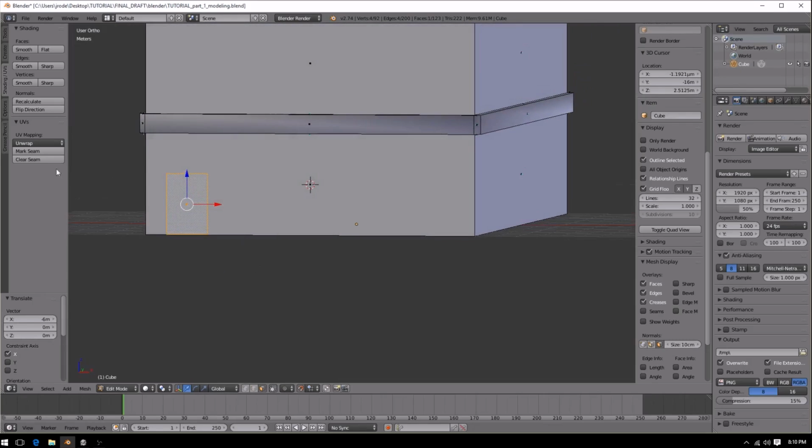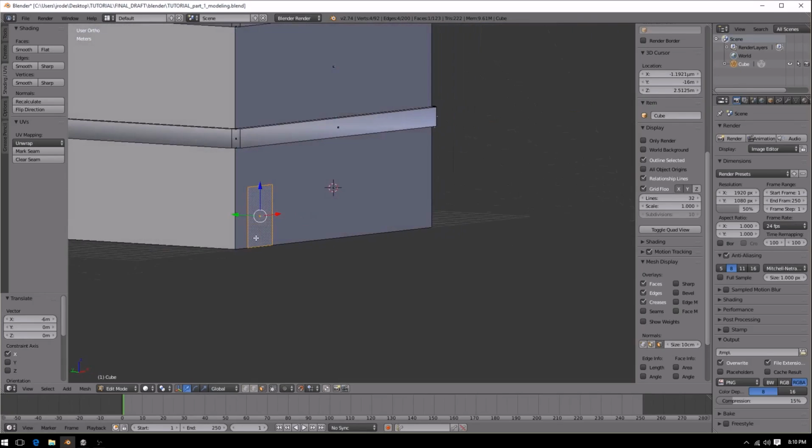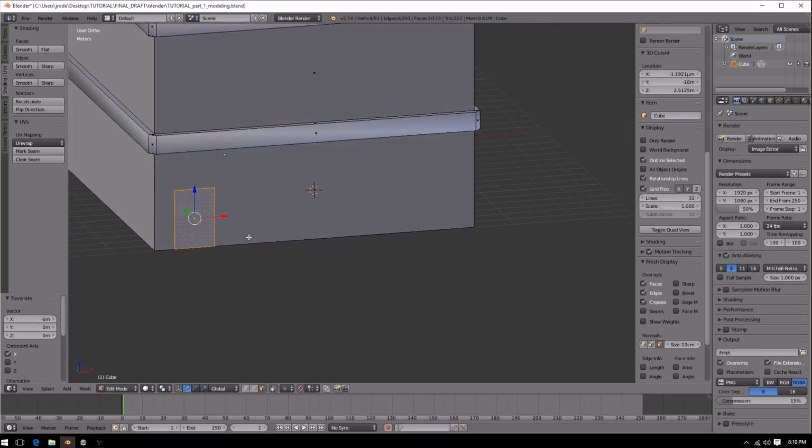That's where I want the door. You can choose anywhere you want to put this door. And so what I want to do is actually duplicate this plane and rotate this so that it becomes a window. That'll be an easy way to make this a window. To duplicate, while only the plane is selected, you're going to hold Shift and hit D.